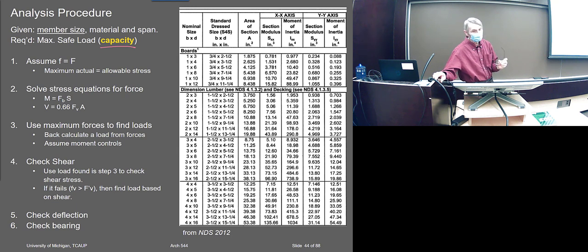And then you can also, by setting the allowable stress equal to the actual stress, in other words, you max out the actual stress on it, take it all the way up to the allowable limit, and then calculate what the moment would be that produces that stress. That would give you the capacity, either the moment capacity, or you can back-calculate it into load or whatever.